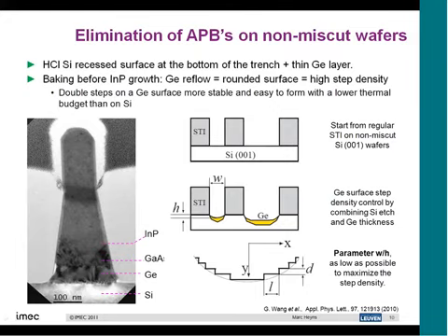We again start with the same STI approach. So we take our silicon wafer and etch out the silicon, but in this case we etch it out a little bit further, so we make a slight hole into the silicon. We deposit germanium on that and we let the germanium flow. And if we have the right etching depth and the right etching width, we make a very big curvature here, and that curvature will translate into double atomic steps, because these double atomic steps give the lowest surface energy of the system.